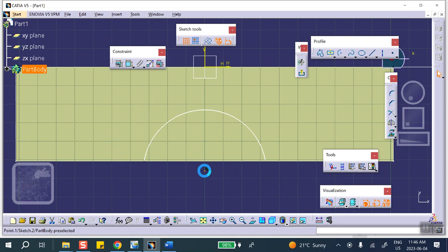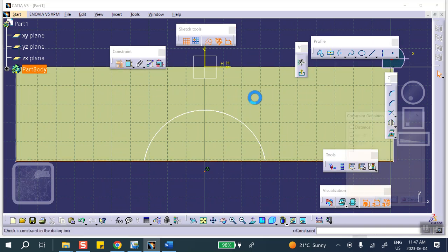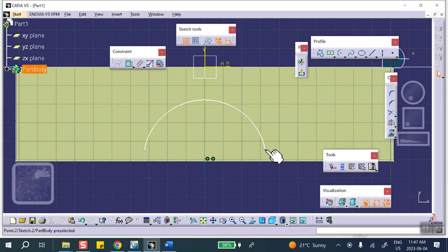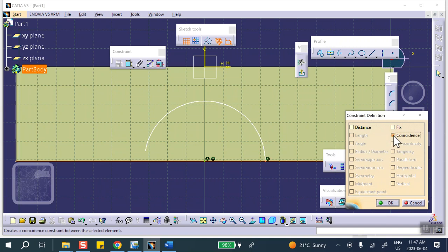Okay. So this point, I want it to be on that line. And there are different ways of doing these things. So let's see, this point, control that line. Coincident. Okay, very good. And I want to bring these things down. This control that line, also coincident. I was not thinking when I was doing this arc, but it can be fixed.